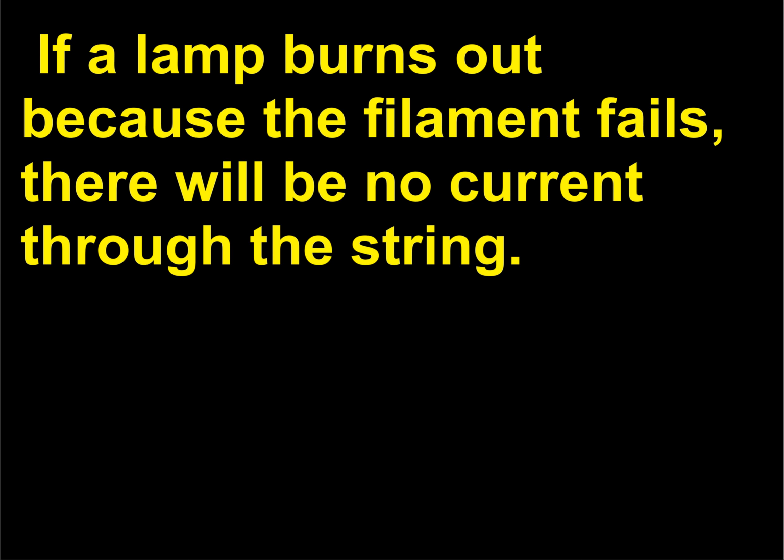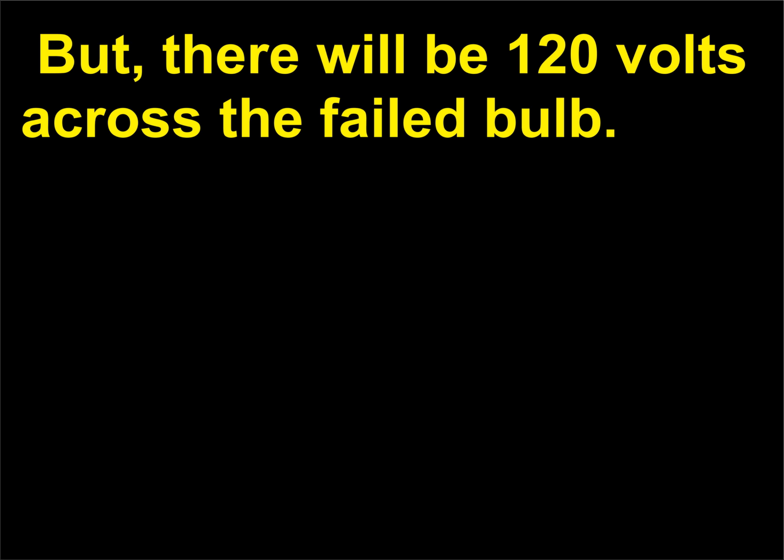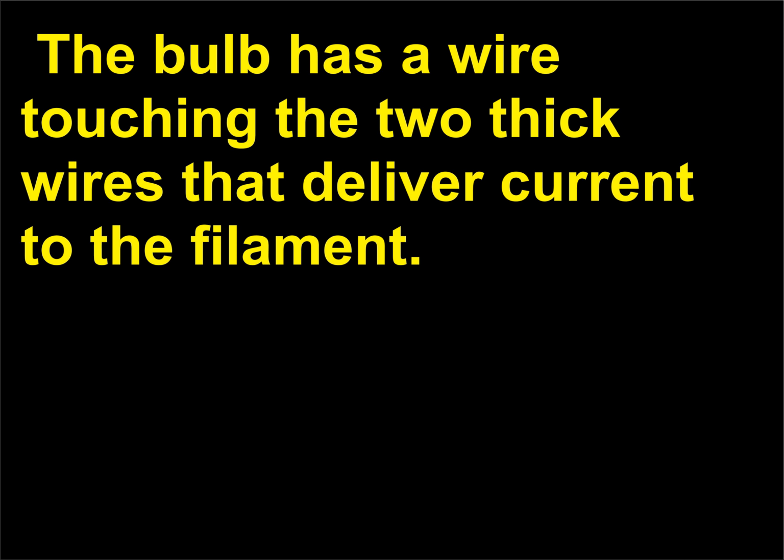If a lamp burns out because the filament fails, there will be no current through the string. But, there will be 120 volts across the failed bulb. The bulb has a wire touching the two thick wires that deliver current to the filament. The wire is covered with a thin insulating film.